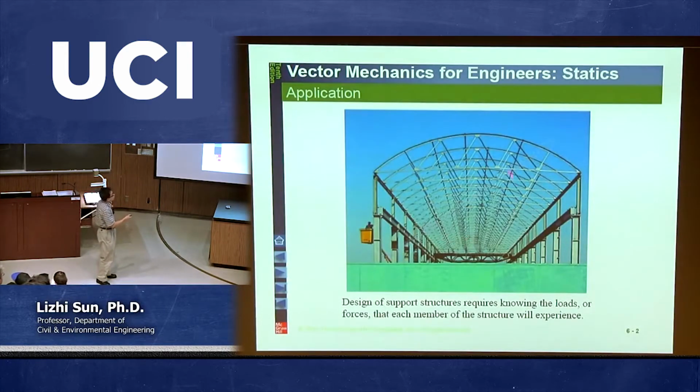So this is the typical truss structure you can frequently see anytime you are walking by the construction of buildings and sometimes bridges and so on, right? Obviously, you can see there are a lot of slender members connecting together to form this kind of structure. The most important reason we normally use a structure composed of a lot of slender members is a cost issue, right? Because we want to save money. So that's why we don't want to use a lot of materials.